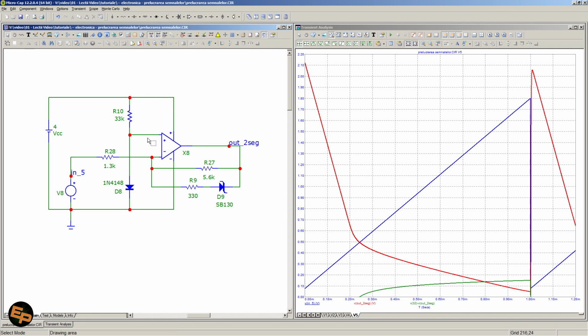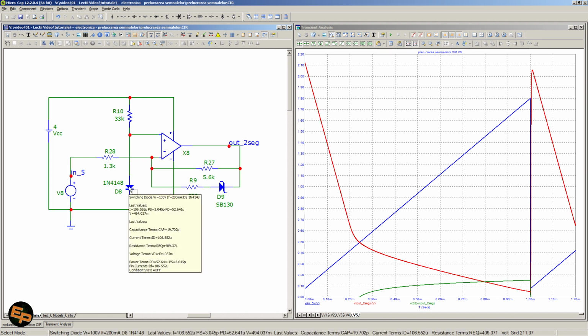First of all, we have an offset voltage on the positive input, on the non-inverting input, and this offset voltage is again created by injecting a relatively small current into a rectifying diode, and that diode will provide a certain voltage, around 490 millivolts in my case, when that small current is being introduced.